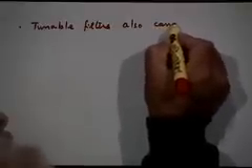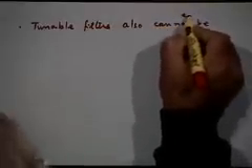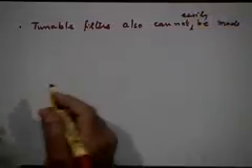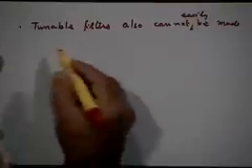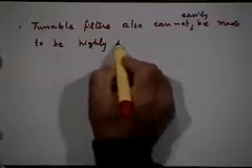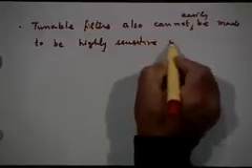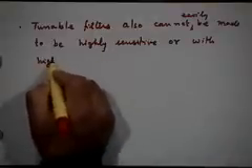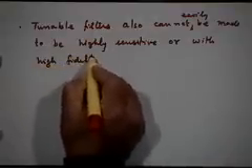So, the other points therefore that I made are that tunable filters of this kind also cannot easily be made. If you pay a price, you can always get everything that you want, but you have to pay a very heavy price in that case. Cannot easily be made to be highly sensitive or, let us say, with high fidelity. So, these are the problems. This is not a key problem, but this is definitely a problem, right. So, tunable filters cannot be made highly selective, they cannot be made highly sensitive, and these are the requirements that you would like to have in a receiver, right.